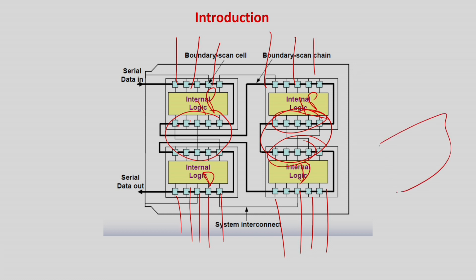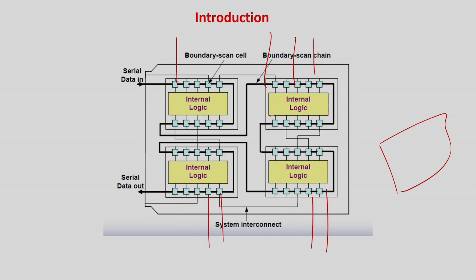Generally this is true not only for IP cores, but for any core based embedded system design, because there will be multiple cores, whether you manufacture them or get them from the IP vendor. In the case of an IP vendor, the problem is greater because you do not have any control over the internal logic. For example, if all 4 cores are designed by you and you want to apply some test pattern here and some test pattern there, I can make some adjustments. Sometimes a lot of test patterns are required to be applied to a pin, so I may try to make it an input output pin. I can put this block here so that there is a direct input output connection.